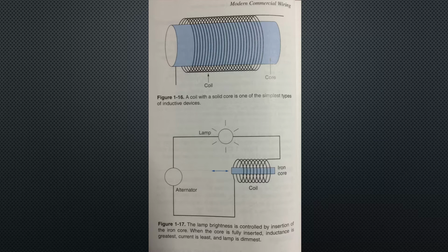The major difference between an AC circuit with resistance alone and one with inductance is response speed. The current flow in a circuit having only resistance will change instantly if the voltage changes. Current flow in an inductive circuit will respond slowly if a voltage change occurs. This opposition due to inductance is called inductive reactance. It is measured in ohms, as resistance is.